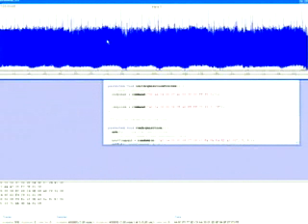So we've taken a couple of hundred measurements now, 500 to be exact. But one of the problems is with these kind of measurements that when we perform our statistics, we do it on sample columns. So we take one sample column of 500 traces and we run our statistics on that. But after these measurements, which are still pretty raw, we don't have the perfect alignment yet. So there's a little bit of jitter in the time. So the first thing we need to do is get all these traces aligned. I'll show you exactly what the problem is.